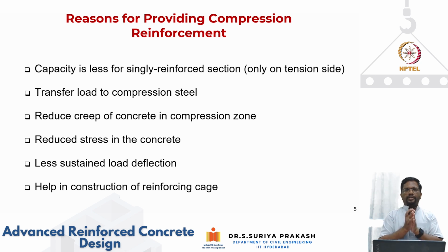So to optimize the cost of construction, we try to keep the size of the beams as nearly the same as possible, and we group them depending upon the load requirements and so on. We do not deviate the size of the beams too much, as much as possible.